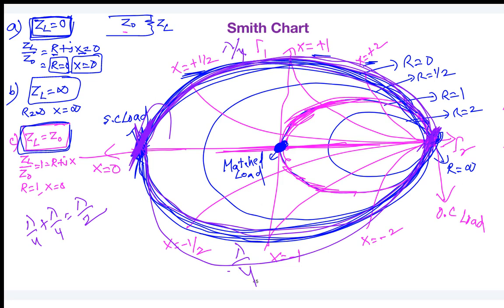That's it, right? So that is why I was telling this. See, you are having a transmission line. At the load end, I had a phase shift of 30 degrees. After traveling a distance of lambda by 4, can you tell me what phase shift it is going to take? Pi, sir. Pi. Pi plus 30.